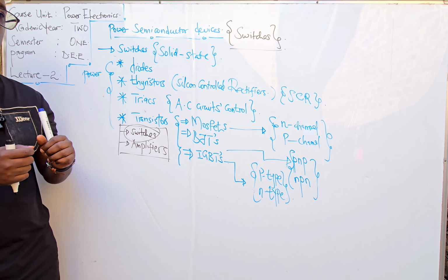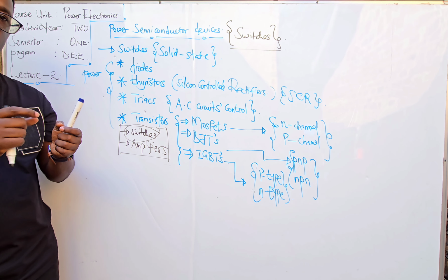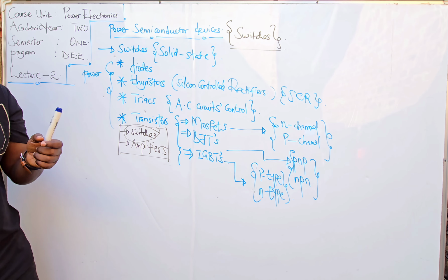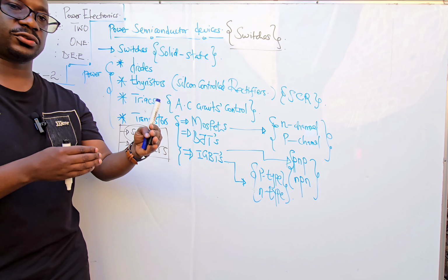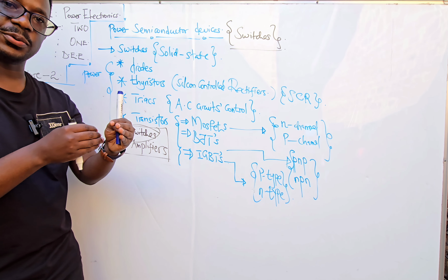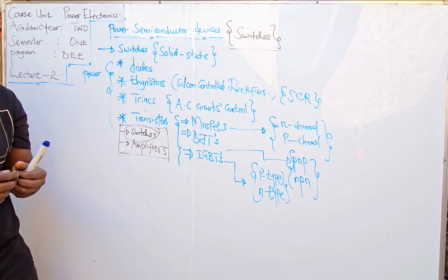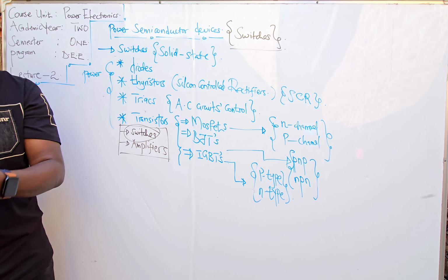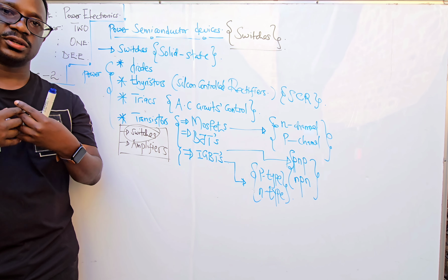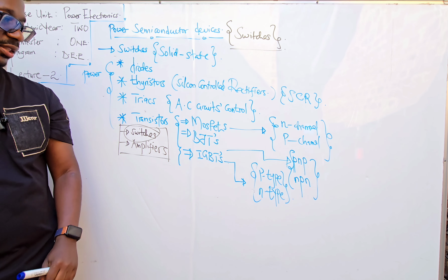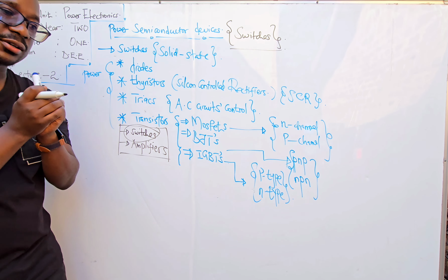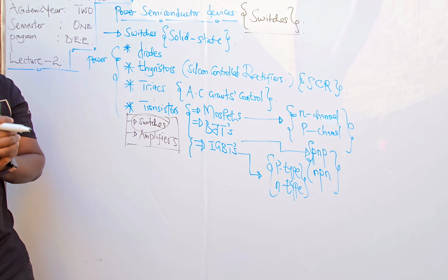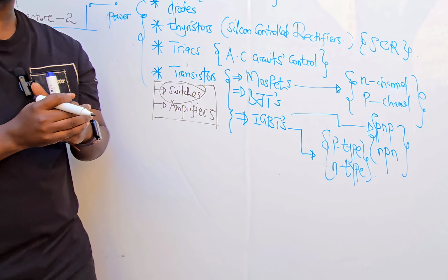So at one point, we will need to adjust how much voltage goes to the batteries to charge the batteries, hence manipulating the current. So that way we can manipulate the power. If you've ever heard of common terms like MPPT, maximum power point tracking charge controllers, these are nothing but circuits that convert power from one voltage to another at a specific current to give a specific power output.